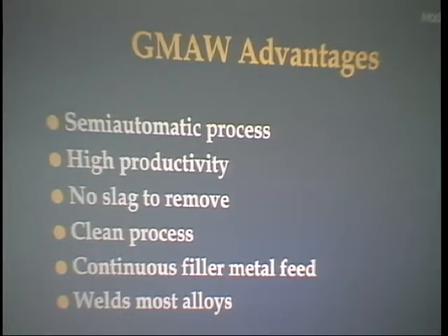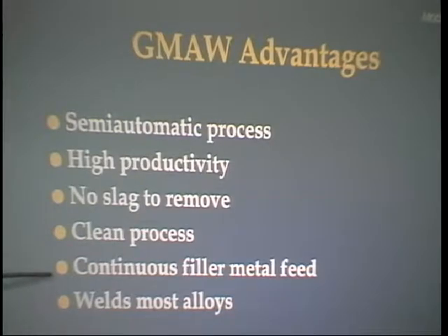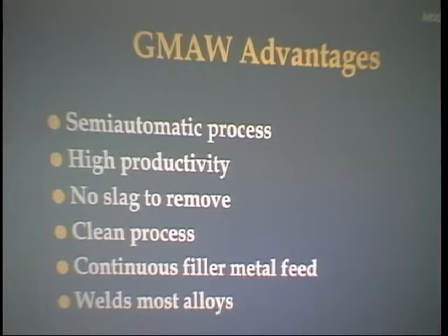Gas metal arc is a semi-automatic process. It produces high productivity. There's no slag to remove. It's a clean process. It's a continuous filler metal process, so you don't have any stubs left over that waste material. It'll weld most alloys. It's also easy to learn, and it's one of the cheapest processes out there. So those are some advantages of it.